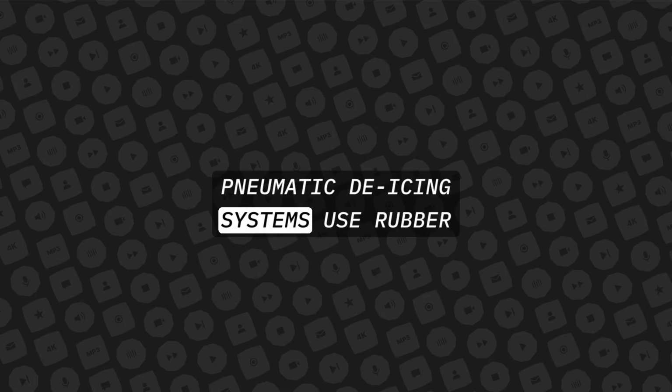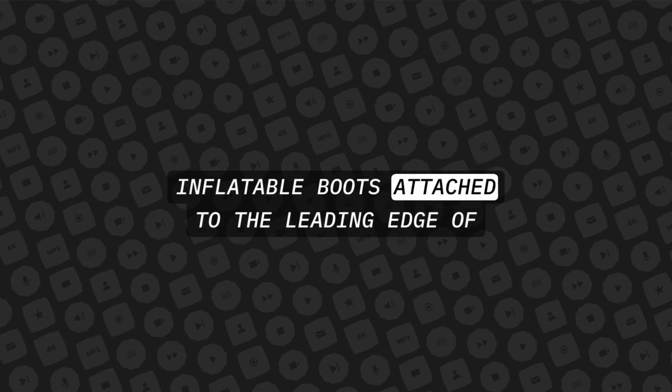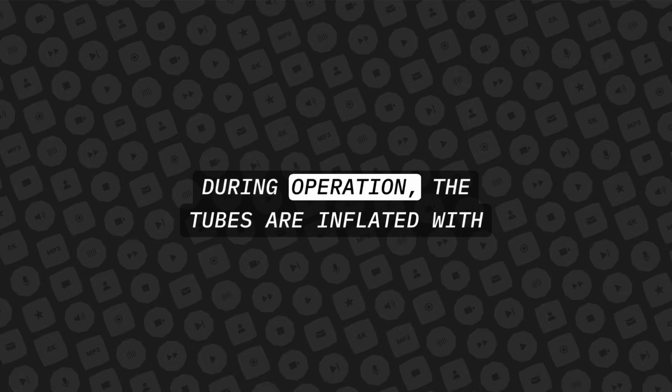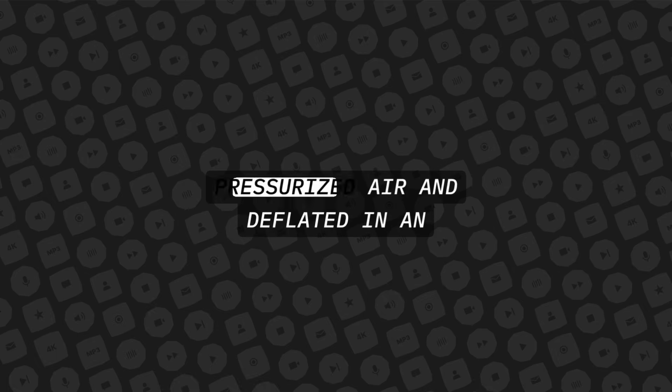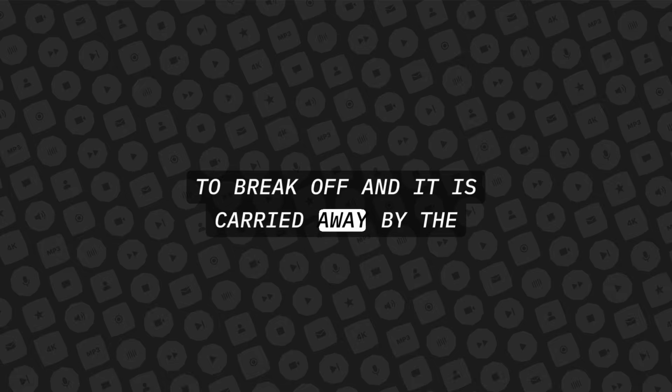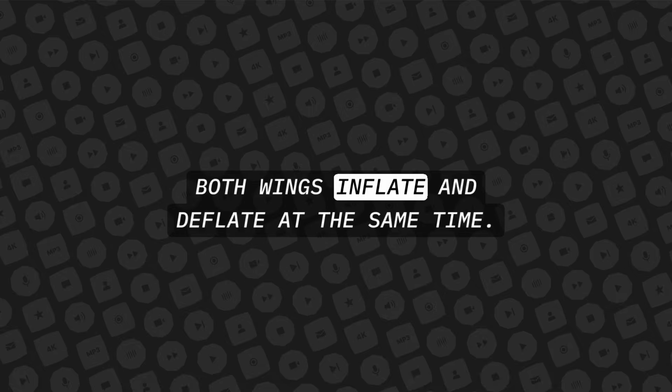Pneumatic de-icing systems use rubber inflatable boots attached to the leading edge of the wings and stabilizers. During operation, the tubes are inflated with pressurized air and deflated in an alternating cycle. This inflation and deflation causes the ice to break off and it is carried away by the airstream. Both wings inflate and deflate at the same time.